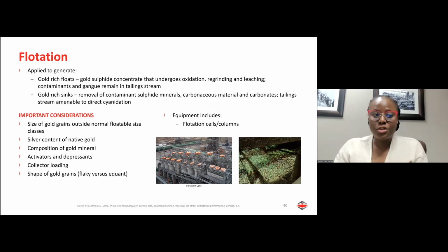Okay, then flotation is a concentration stage that removes undesired material from your stream. So for example, if you have a stream where your main minerals are gold oxides, then flotation will remove your sulfides and your carbonaceous contaminants in the floats. It is then up to you, when you are doing the design of the plant, whether you're going to then treat those floats or discard them.